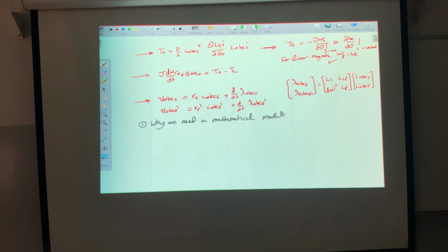If you recall, the DC machines were very simple. The relation is very simple. The torque is proportional to the flux and the armature current. So I can manipulate the armature current by manipulating the voltage, so I can control the torque, so I can control the speed, correct? Now here, I cannot. It will be very difficult. This is the first thing. The second thing, if I look at the voltage equation, I can't understand anything from it, if I compare it to the DC machine.